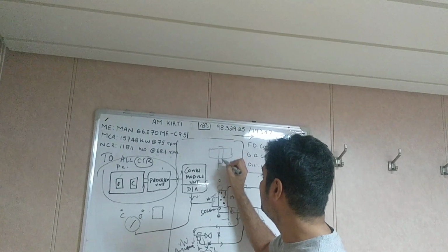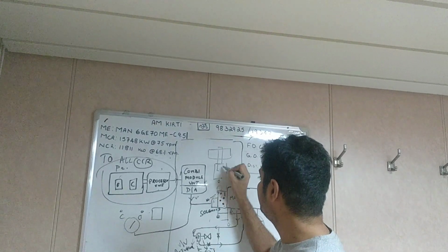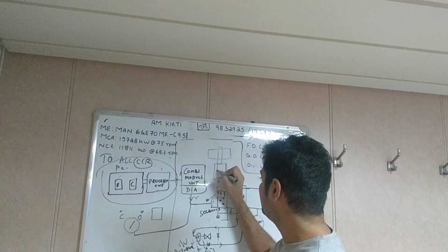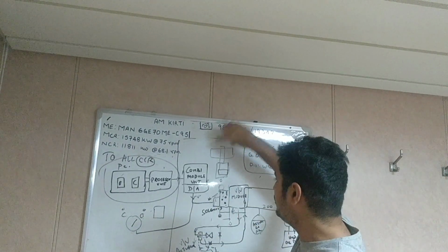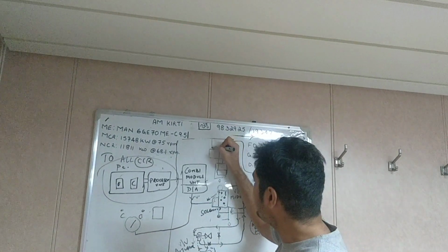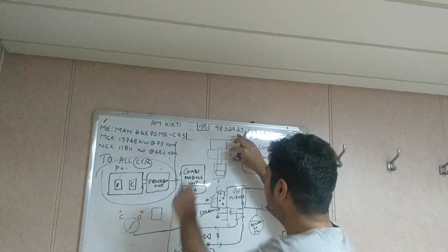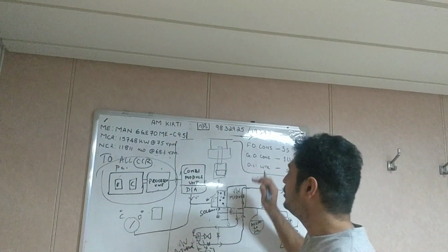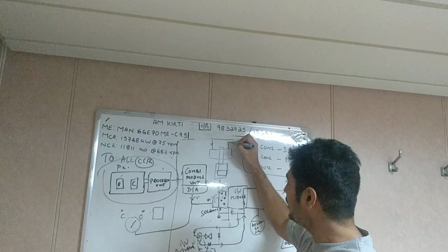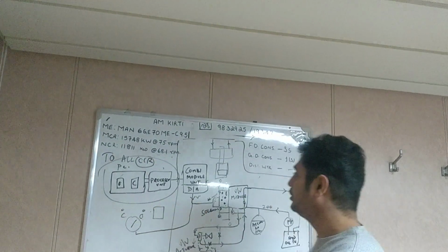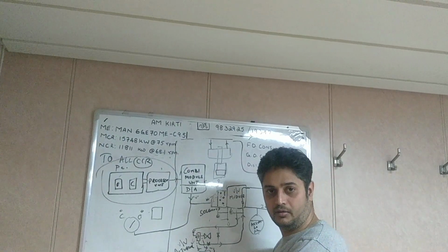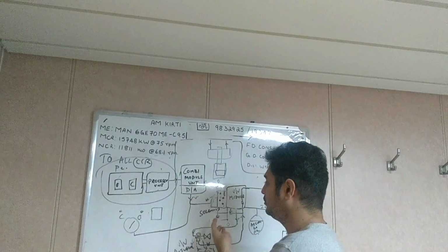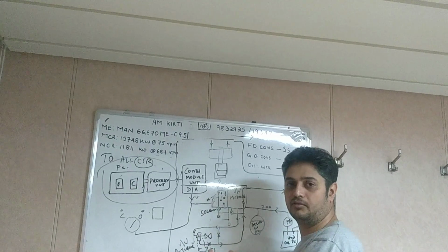Just assume this is the valve. Something like this. You can remove this actuator. The actuator has connections, so remove the actuator from its place. Connect the oil supply. Give the command from the local hand pump or through this. It's better to do it from the hand pump.